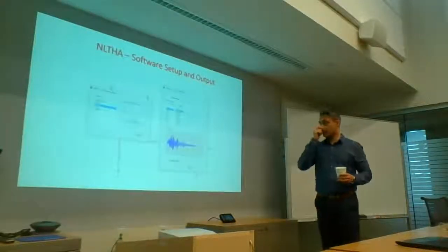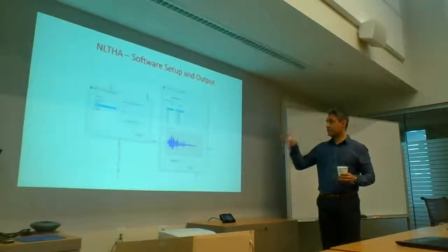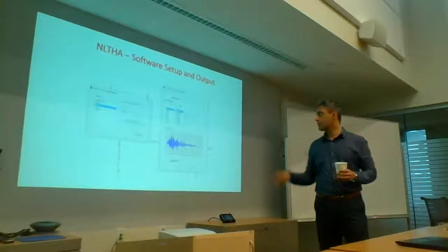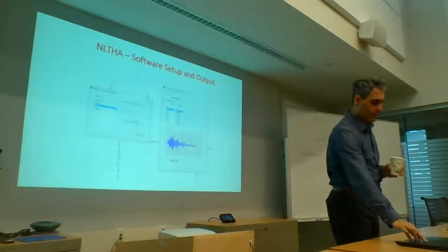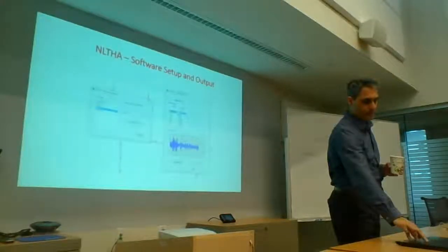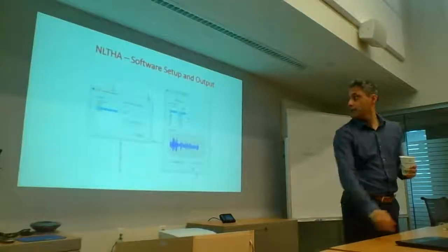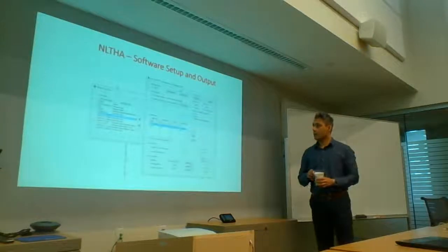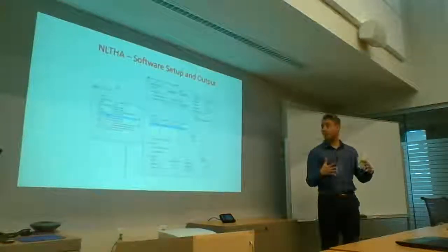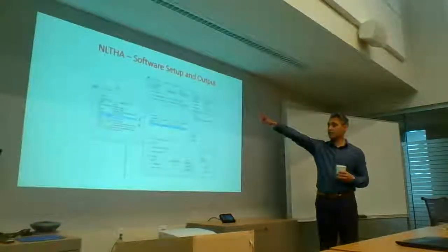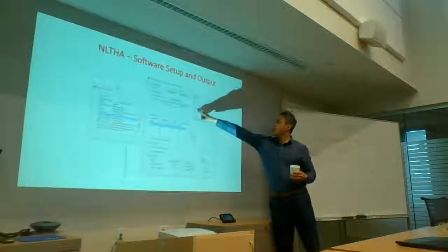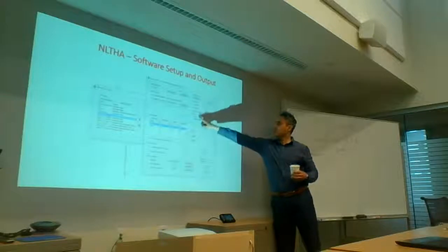So this is my time history in the X direction. You can read it through an Excel file. Of course, you're not going to put every number into it. There are ways of doing that, and those are software specific. This is the time history Y. Now this is where I apply the two simultaneously. So that's the time history X and Y. Okay, so this is a nonlinear time history case. I'm not accounting for any geometric nonlinearity.